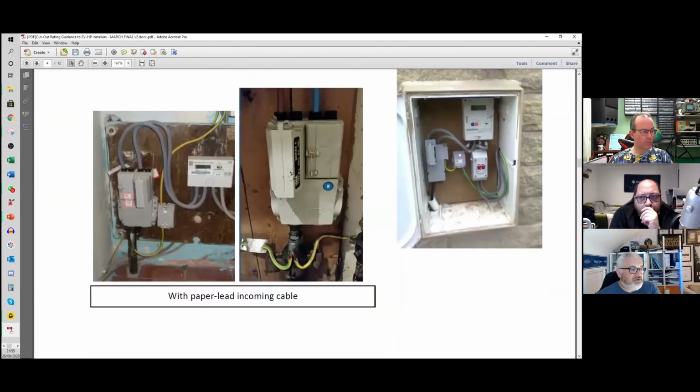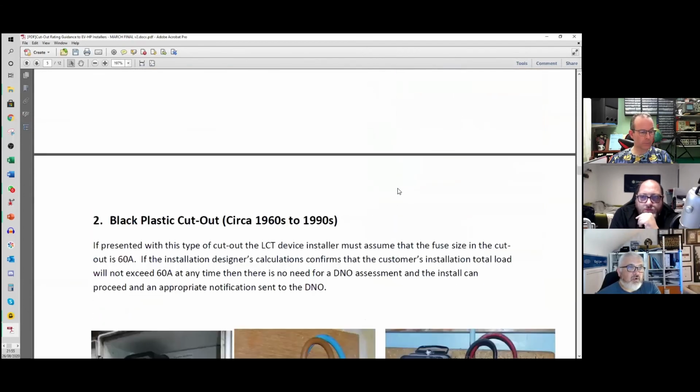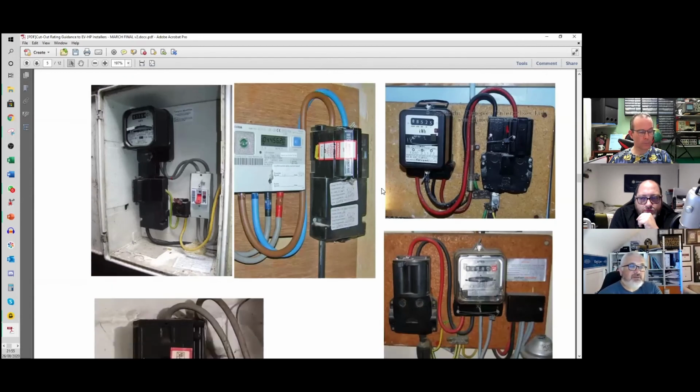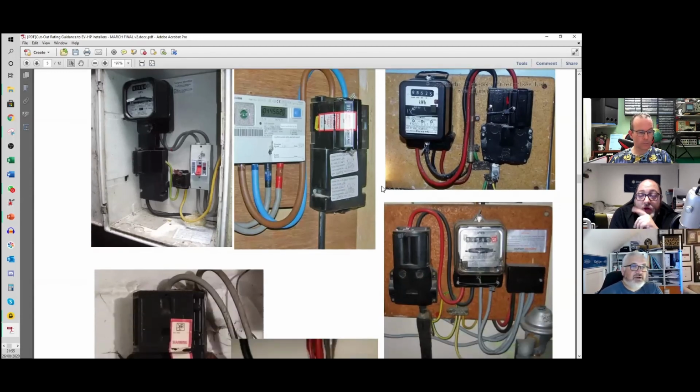Different configurations. You notice all of the earthing terminals are plastic now. Insulated, yeah, they're all insulated. That's because there's reference to insulating anything which could become charged or energised, which we're going to cover. Good wording there. Charged. Live is charged, which means it doesn't necessarily have a voltage on it. It could be 0 volts, but it can have current flowing through it. And HSG 85 does define anything that has significant charge as live.